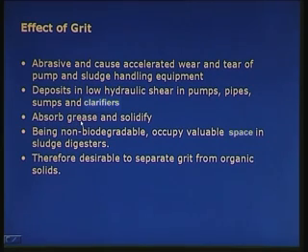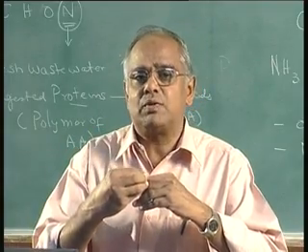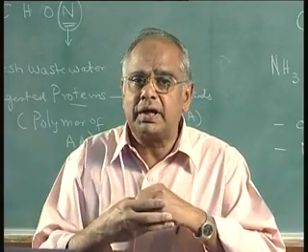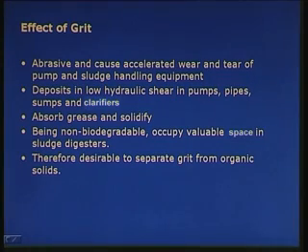This grit has another property: it offers a lot of surface area, and because of that surface area, the oil and grease present in the wastewater gets absorbed onto the grit. As a result, it absorbs grease and they solidify, and grease balls are produced.